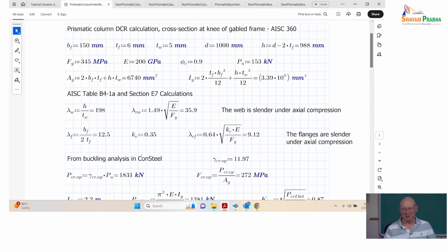Dr. Pekoz basically observed in his research that he could get an effective moment of inertia and an effective area, and then a radius of gyration, square root of I over A. And he said, gosh, I'm getting about the same radius of gyration as the gross, so why don't I just use my gross section properties to get my column stress? So that's the approach, right or wrong. You can say all these approaches are either right or they're all wrong. It's not science, right? It's engineering.